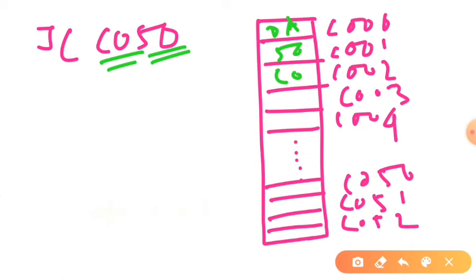Obviously. Now we need to inform the microprocessor the starting memory address C000 of this instruction. Once the microprocessor is informed, it will start fetching the instructions from C000. It will fetch the first instruction, that is DA. It will understand that it's obviously a conditional jump instruction.